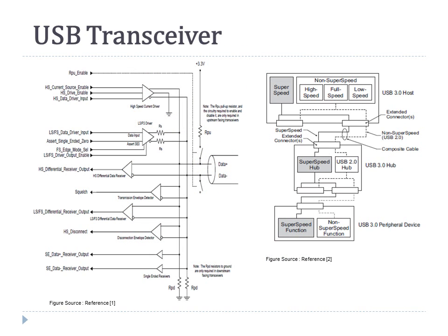Here we see the USB transceiver on the left. This is the USB 2 transceiver. As you can see, there is separate circuitry for high speed: this is the high speed transmitter, this is the low speed and full speed transmitter, this is the high speed receiver, and this is the low speed and full speed receiver. This architecture also helps to maintain the backward compatibility. If the device is only low speed and full speed capable, it just has the low speed and full speed transmitter and low speed and full speed receiver. The high speed part is not there.